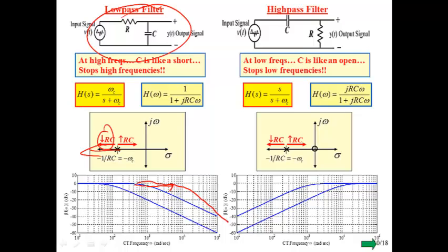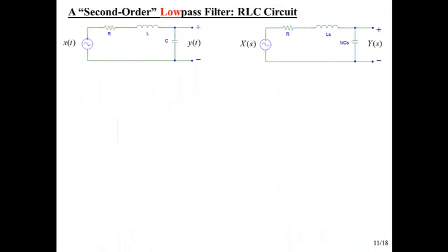And so what that says is, if we want a circuit to respond rapidly to a transient input, we want it to pass very high frequencies. And we've seen that idea before too. Input signals that have rapid changes contain high frequencies. Therefore, to get those rapid changes through the filter, we want it to pass high frequencies. So a lot of these ideas are starting to come together and make sense here, hopefully.